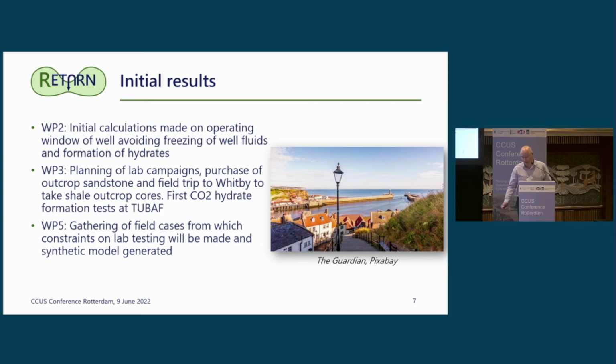So work package 2, you'll see in a minute. It deals with looking at the flow models from coupling the well where you're injecting the CO2 and the near well area, the reservoir. And there we've had some calculations made principally by EBN here in the Netherlands, and some of them by University of Cambridge, looking at what are the windows of operation where you can avoid, on one hand, freezing of the well fluids, and on the other hand, formation of CO2 hydrates in the near well zone.